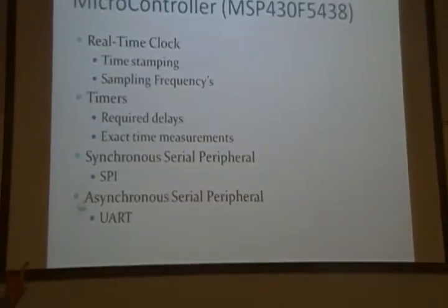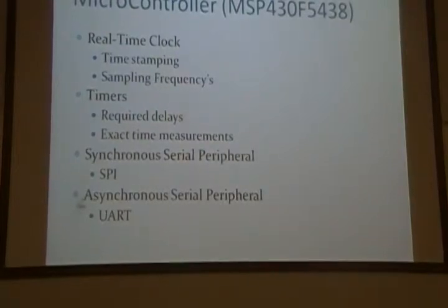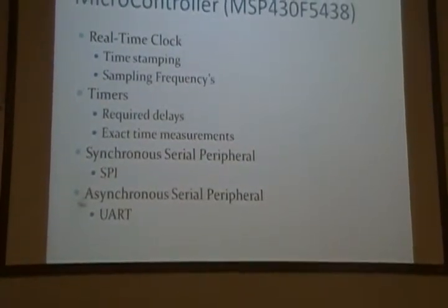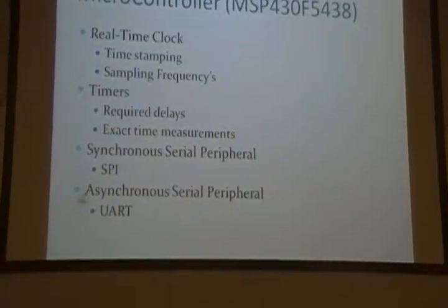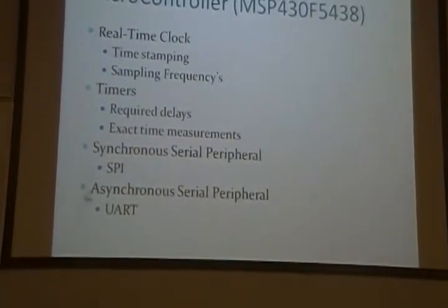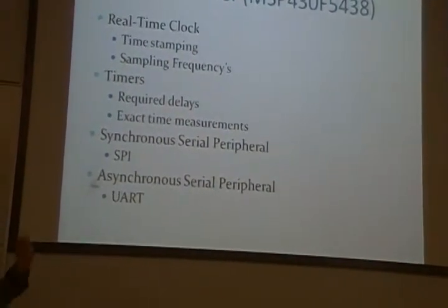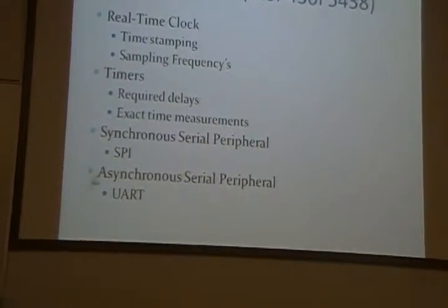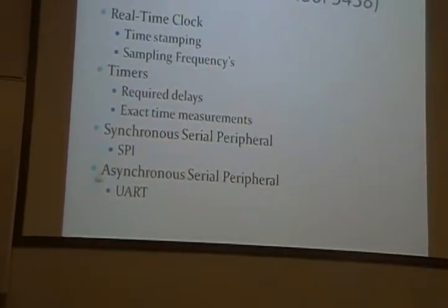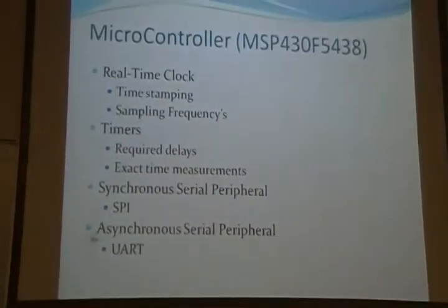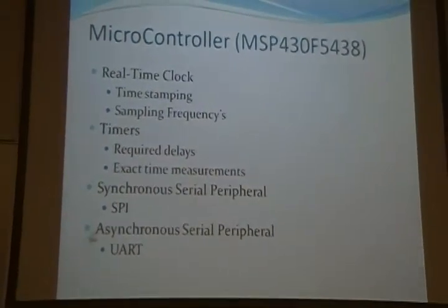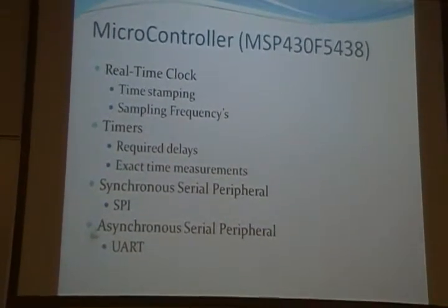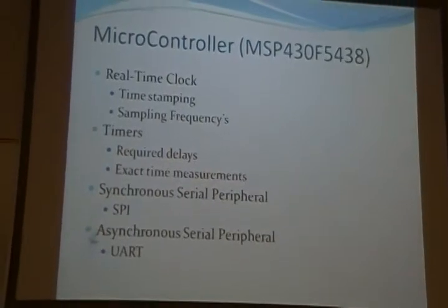And this is the microcontroller we picked. We use its real-time clock for time stamping and implementing sampling rates. We use timers to measure exact times and provide required delays. And we use the synchronous serial interface for SPI communication and asynchronous for the UART.